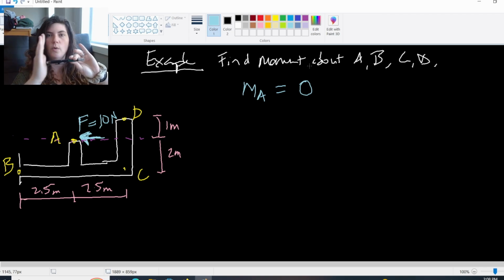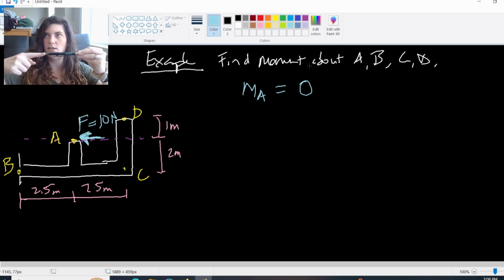It wouldn't turn, it wouldn't go anywhere, right? All of your force is acting right on the line of action. And so it's feeling the force pushing it this way, but there's no rotational movement about the point where your nut is sitting, right? If you put the upwards force or the downwards force, you can see the rotation in my pin. But if I put a straight line of action within the line of action about my point here on the other side, there's no rotation. So the moment, if the point is within the line of action, is just going to be 0.